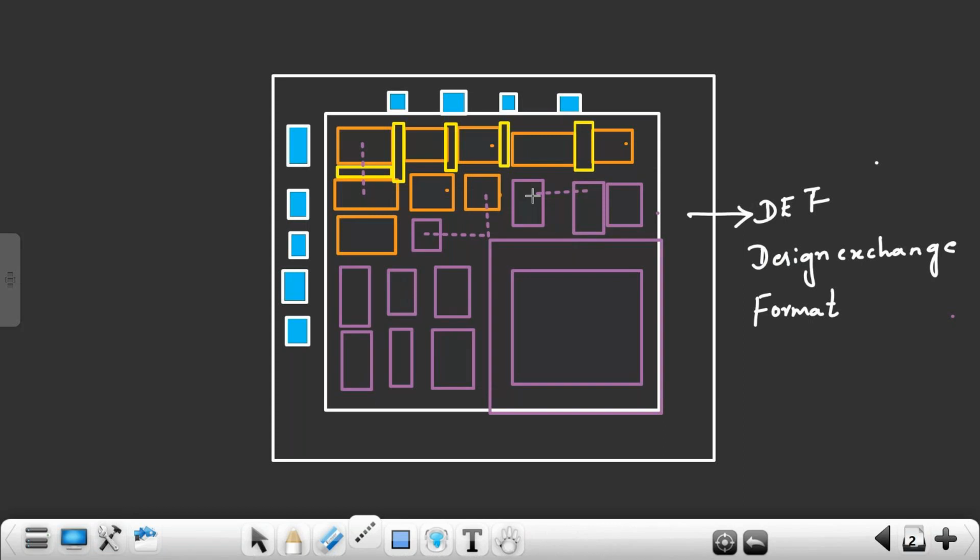While creating the core area and die area, we would have used utilization, keeping those cells in mind. For example, 5% of cells can be added in the place stage, 5% in the CTS stage, and 5% in the routing stage. So you keep 15% extra space and then proceed with the design, right? That you have to take care of while building.